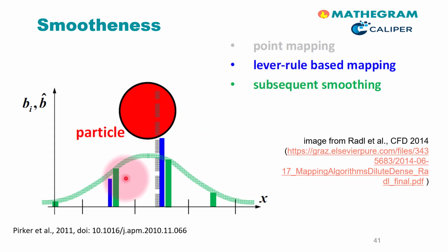What is done in smoothing is that the mapped quantities are redistributed in the surrounding cells, similar to the physical process of diffusion, but with an infinitely fast diffusion rate and over a certain smoothing distance that the user has to specify. As shown in the recent review of Calderon et al., the quality of the resulting continuum property field, e.g. the porosity field, is much better in case of smoothing. In short, investing in such a smoothing operation is worth the effort.